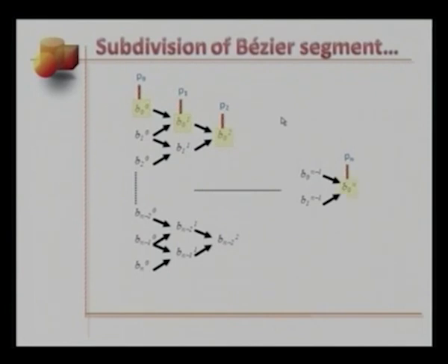Likewise, the final point for a value of c now here. So remember that these intermediate de Casteljau points are for u equals c. Stage n, which is the final point on the Bezier segment for u equals c, is our design point P sub n.